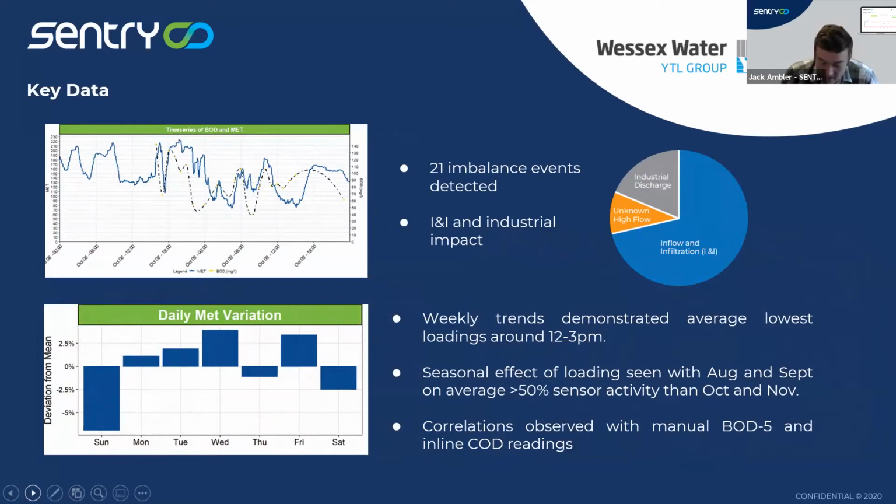For them, they were really trying to target these BAF systems. They're a little abnormal, maybe not super standard for the wastewater industry. Very interesting technology, it basically does biological treatment and physical filtration in the same step, so you don't need a secondary clarifier after it. It has a lot of small beads in it that you upflow water through. Really a good piece of equipment, just very energy intensive and very maintenance intensive. They have 5 of these systems running simultaneously and are trying to figure out when they can bring one offline, or potentially up to 2 offline.